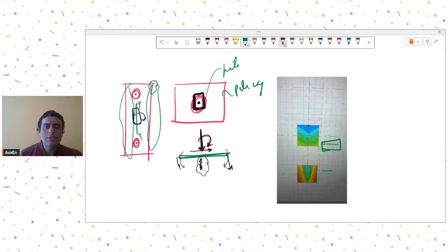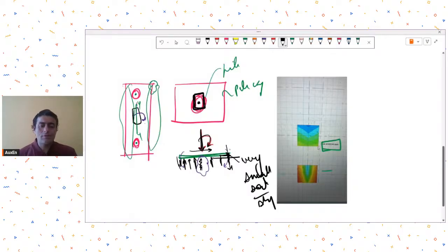So what do we generally do in such cases? It is good to provide soil stiffness below, so that it will try to balance out some deflections. But even then you may get large deflections. Why? Because generally very small soil stiffnesses are provided, because you don't get large bearing capacity of your soil at the pile cap bottom level. So you still may get very large rotations, and because of those large rotations you may get very large deflection values. So this you need to check first of all. I mean, this problem you need to understand.